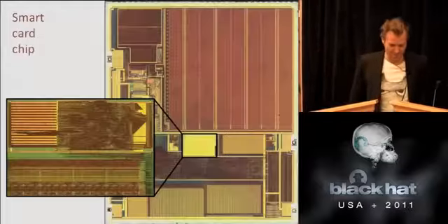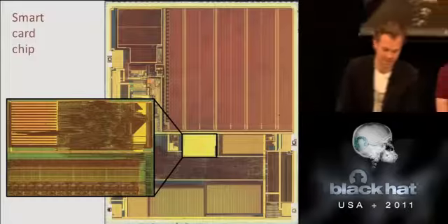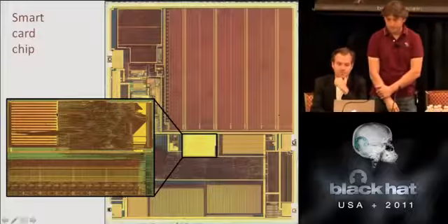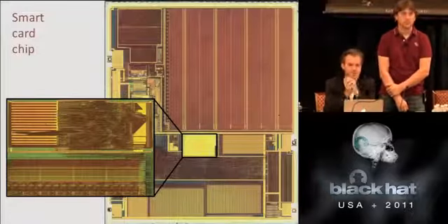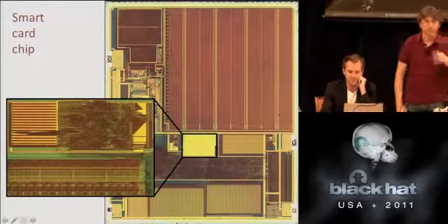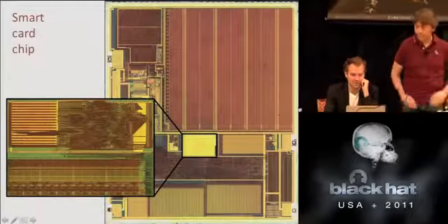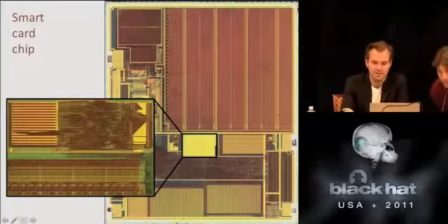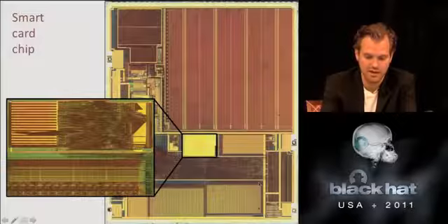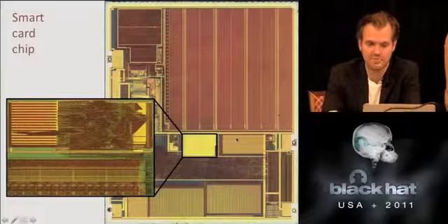But let's look at a smart card chip as an example for many other smart card chips, since they're all pretty much built the same way. A smart card is a full computing system scaled down to a single chip. It will include a CPU core. It's hidden under this plate of metal. So this is the CPU core on this chip. It includes memories. So there's a read-write memory over here. There's some read-only memory here. And then there's 2 portions of RAM. So really everything you would expect in a normal computer.